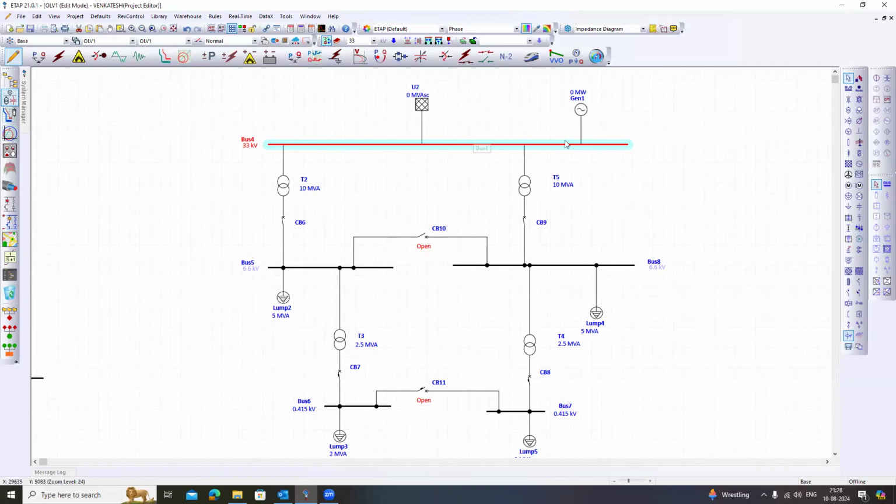Like in that generation category, again the same. With this generator, whether you are able to meet the complete load requirement with this single generator. In that case, again, you have to perform these cases at 100% and 95%, and that is completely depending upon your generator parameters. What is the maximum and minimum voltage variation that is allowed in the generator data sheet? According to that, you have to create the different cases.